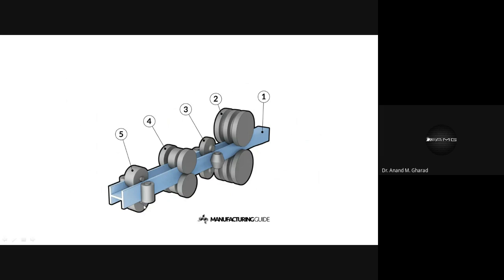So, because of this sudden variation in temperature, there may be certain amount of stresses involved in it. Those are known as residual stresses. Because of the sudden cooling effect, some amount of inbuilt stresses will develop.